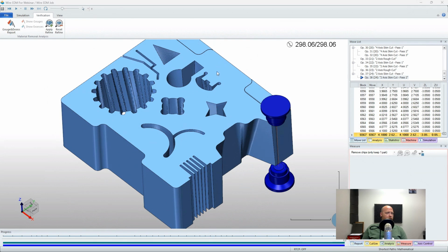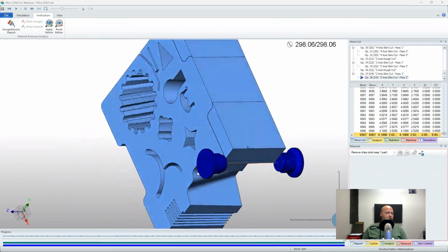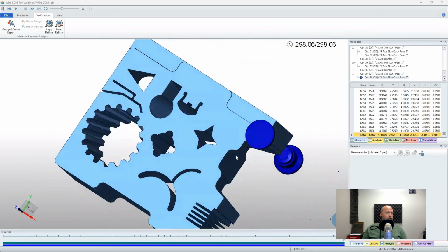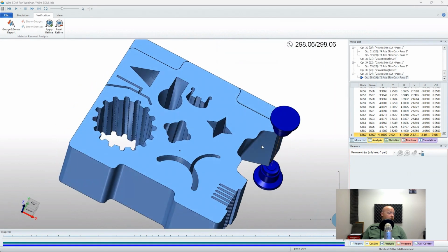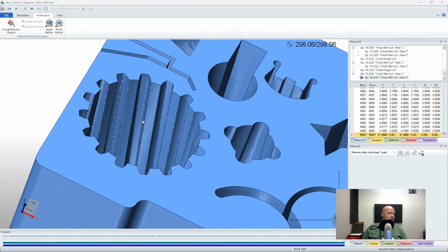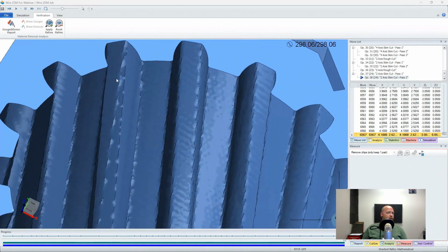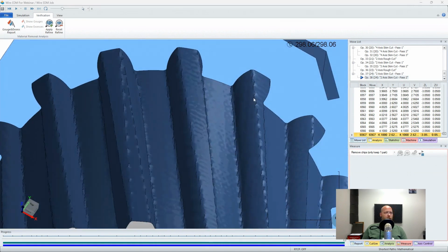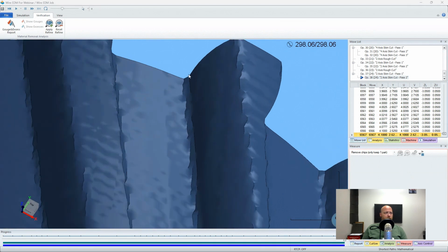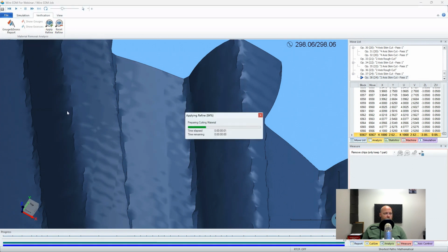And then why are we not getting rid of those side pieces? All right, whatever. I'm not too worried about it. Yeah, there it is. And if you zoom in, when you see real bad finishes, zoom in. Make sure you look at them because a lot of times it'll clean it up. So you just wait. There's a thing that usually pops up down here, says automatic quality improvement, or you can go up to the verification tab and say apply, refine.